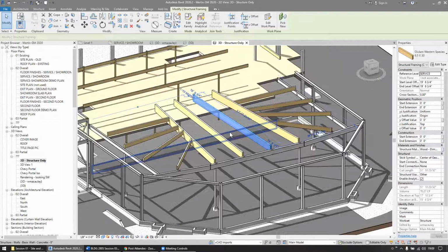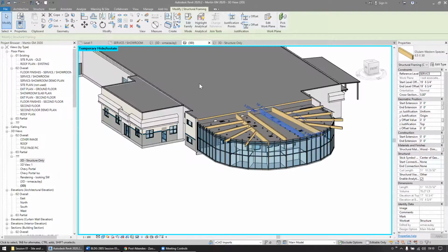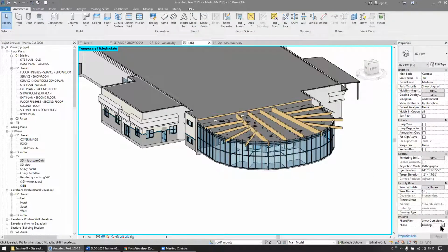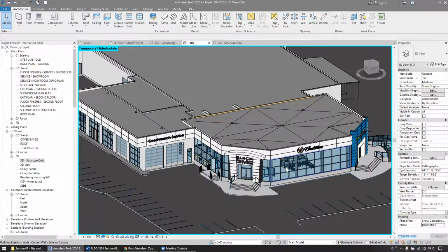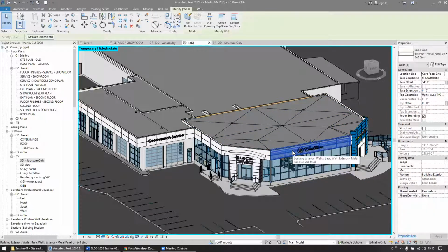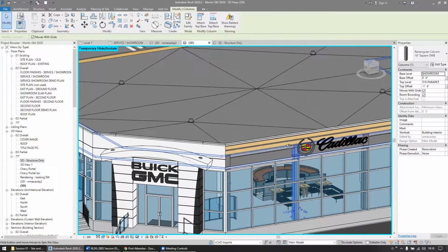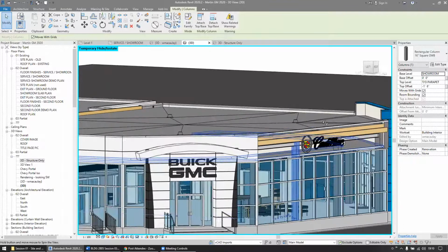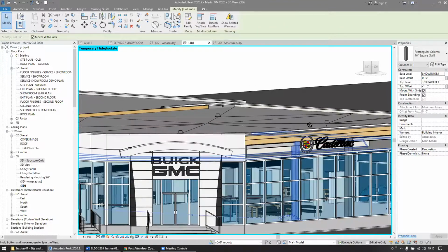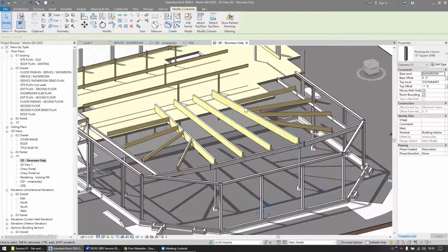glulams, running down to the front of the building. So here, let me get the later phase up here. And so what they wanted to do was get that ductwork here in behind the front curtain wall, right up in behind these columns here, so we can kind of peek inside there, and you can see there's that whole bulkhead space. So they wanted to get that duct to come down in between those beams and into this zone here for air delivery into the showroom.